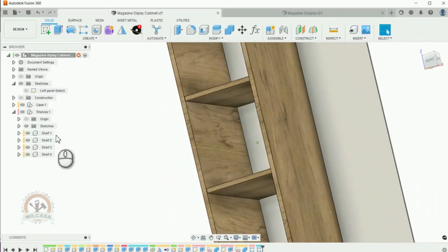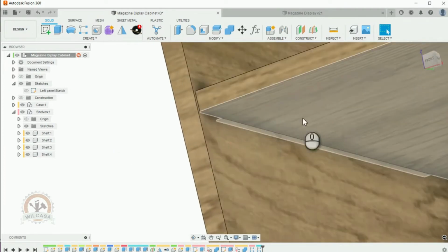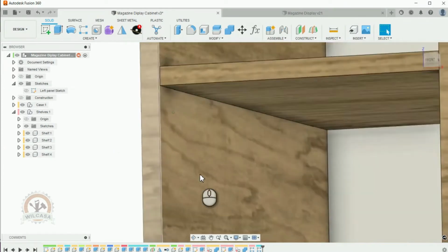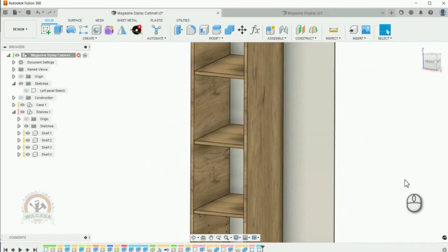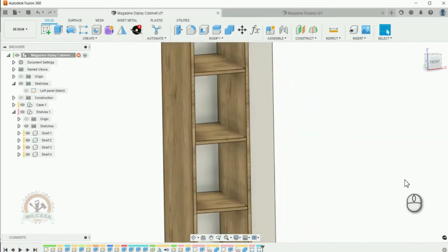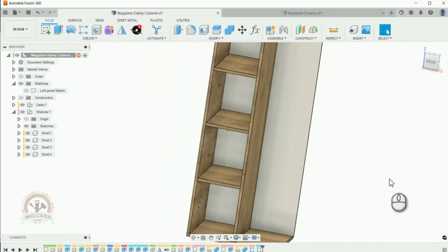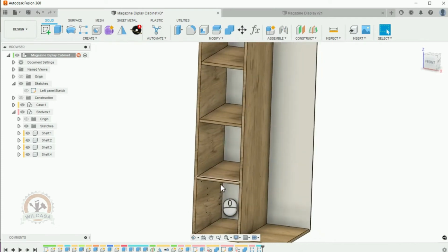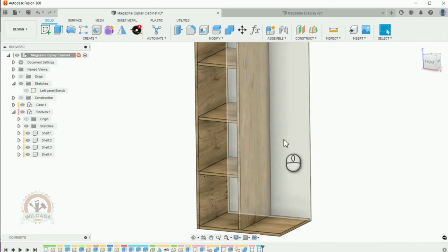If you look on the bottom, it is the same thing. You have all your data where they need to be, but we are missing the ones on the right side, the one on this vertical partition. So let's go ahead and do the first one, and we will repeat a rectangular pattern to create the other ones.